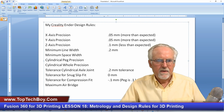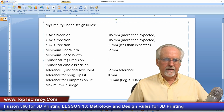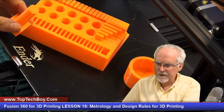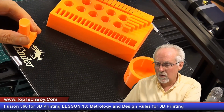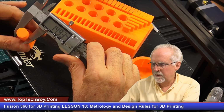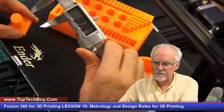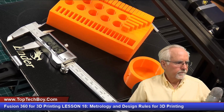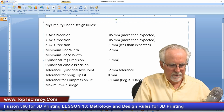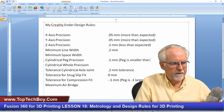Okay, all right. Now let's come back up here and see how precisely I am defining the peg. How precisely am I getting the diameter of the peg? We wanted this peg to be 15, and what it is, is 14.9. So this is 0.1 millimeter, and I'm going to be explicit here: peg is smaller than expected.